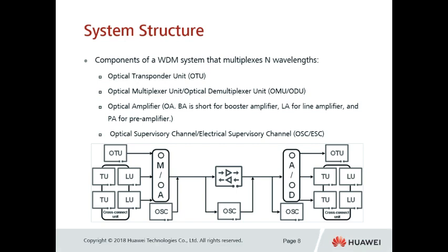For example, for the first OTU board, if the WDM side interface is broken, what should we do for troubleshooting? The only thing we can do is go to the equipment side and use a new board to replace the broken board. Then your service will be restored. But we don't have any other solution to fix your service. So we thought it's pretty dangerous.